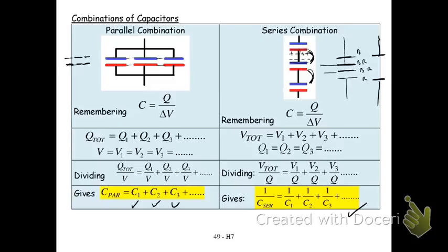So what I learned to do is, you learn one of them. I learned resistances because it's what I was introduced to first. And then I learned that capacitors go the opposite way. And if you've not learned resistances, then you might want to learn capacitances and then say resistances go the other way. But it is the opposite, so you've got to be careful about that. In series, capacitors get less. In parallel, capacitors get more.